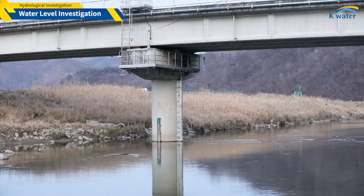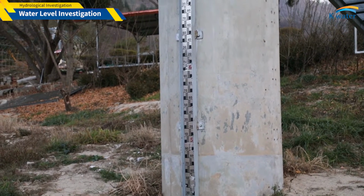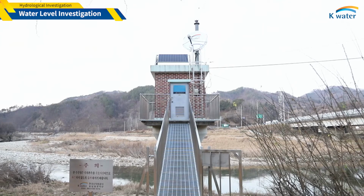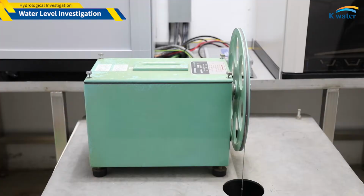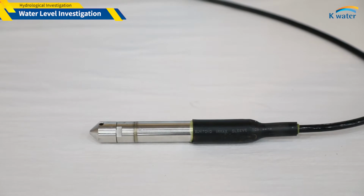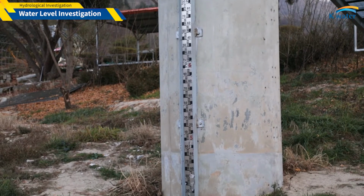What is water level? Water level refers to a measure of the height from a given reference to the surface of the water. Among the various water level meters to measure the water level, let's look at float level gauge, pressure type level gauge, radar type level gauge, and reference water level table.